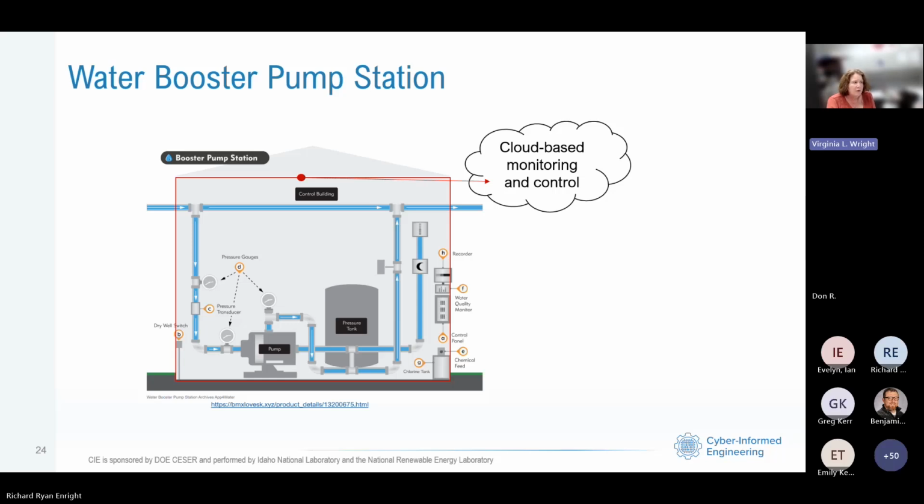But as they thought a little bit further about what is truly the worst thing that could happen, any adversary that could turn a pump on or off could turn it on and off and on and off repeatedly, and might do so so quickly that they either broke the pump or created a water hammer effect with the potential of damaging the water booster pump station.